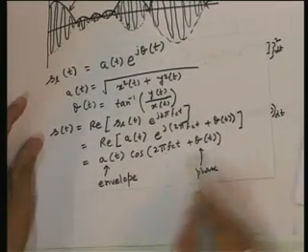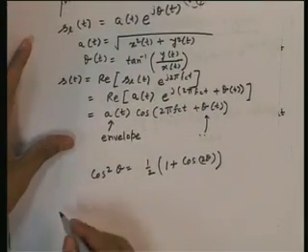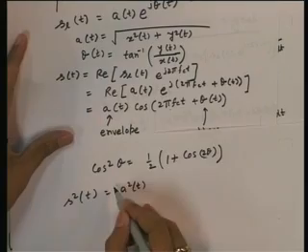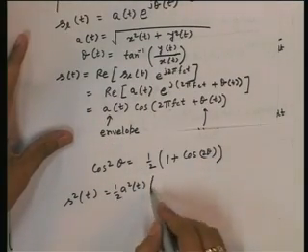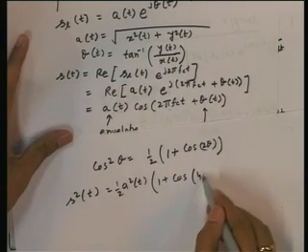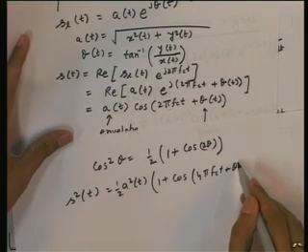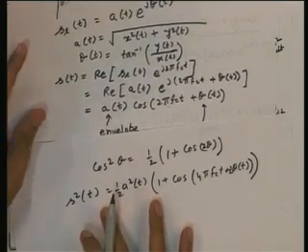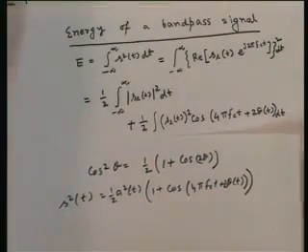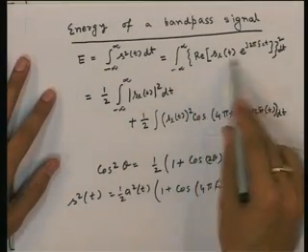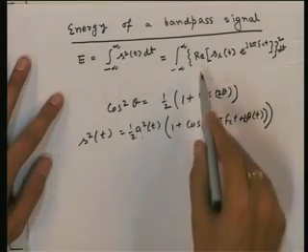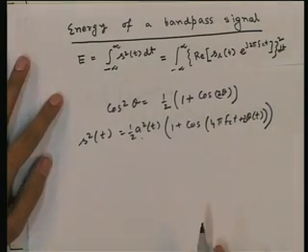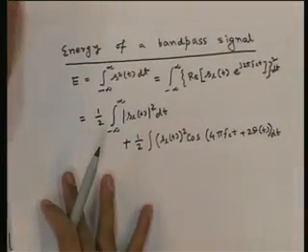So, using that, the square of this is a square t. So, s square t is a square t times half of 1 plus cos of 2 times this, that is 4 pi fc t plus 2 theta t. Now, we integrate these two parts separately as we need here. This inside quantity is this quantity. We need to integrate these two parts, half a square t and half a square t times cos of this. Once we do that, we actually have this.